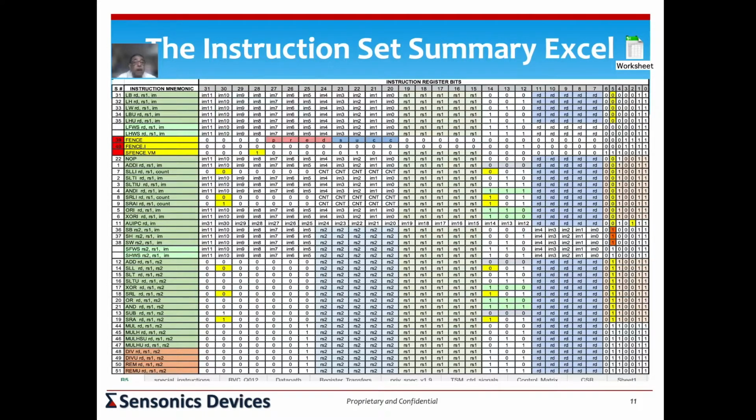So these are instructions that you could add. When you add those, you will have the corresponding opcode bits. And if you made a mistake and you used up opcodes which are already reserved for something else, you would find that purely at the Excel level. So this is something that is worth considering. At least it simplifies and eases your design verification phase after the logic design is done, and you're able to do it at this level.